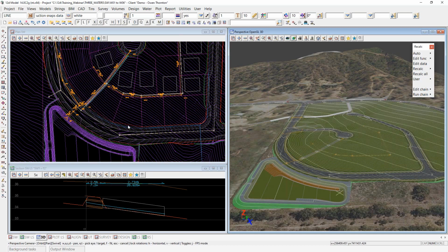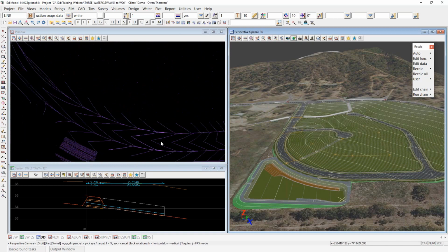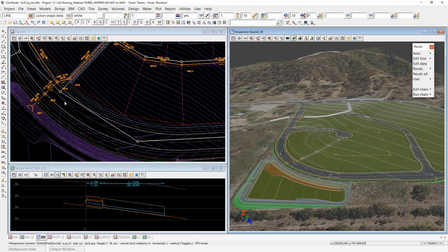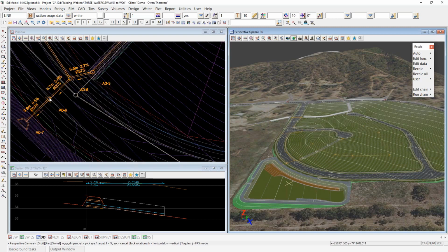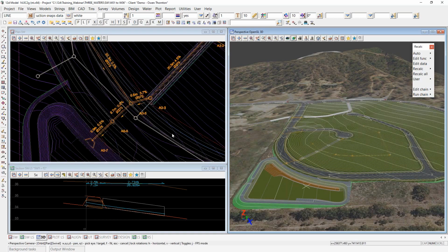and then use possibly a variation in your road design file that references the center lines, a string in the middle of your road, because ultimately it's more important to have that center string representing the center of the carriageway. Arguably it's more important to know, for each node, which side of the road it's on from a hydraulic perspective.